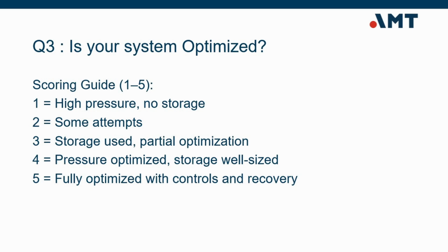Storage is not backup air. Storage stabilizes the system and reduces cycling. A fully optimized system uses controls and storage together, so compressors do not chase short-term spikes. Score your system using the guide.